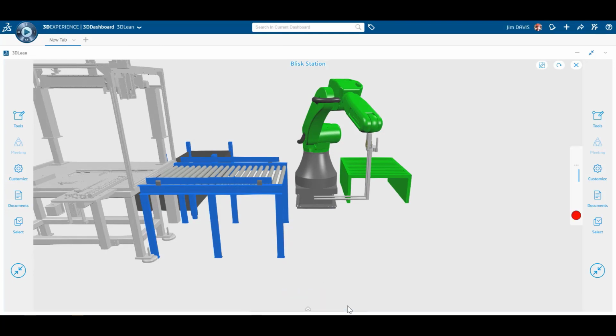And so in our particular case, we've been used to setting up the robot arm where it's taking more of a horizontal across and then down path. And that might have an impact in the way it scratches or touches the material as it's coming off the end of this conveyor. So perhaps what might be better is if we took a configuration change and made it so that the robot arm came down and then across as part of the new path that might change that. So this is something that we might want to put into action.